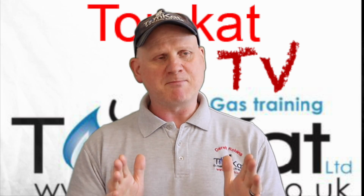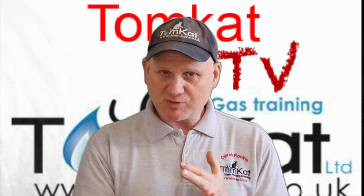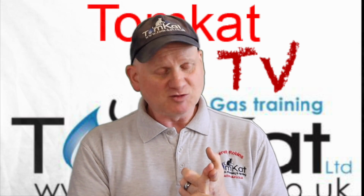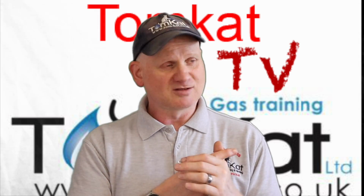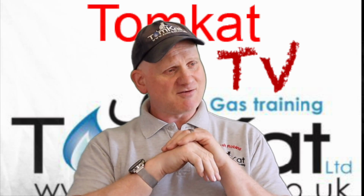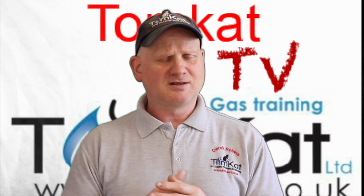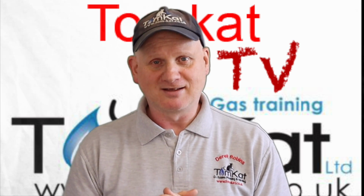But just remember, if it's spilling products of combustion, if its safety devices have been made inoperative, if it should be flued and it's not, if it's got the wrong gas, so if it's LPG on a natural gas appliance or natural gas on an LPG appliance, these are immediately dangerous situations. If it's anything else and you can't find it in the book, then it could be not to current standards. It's as simple as that.